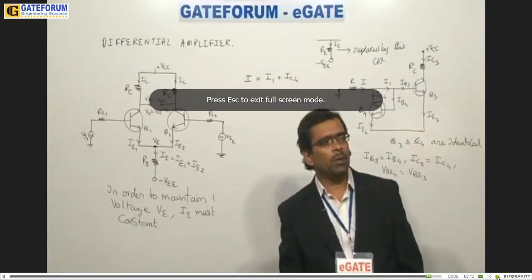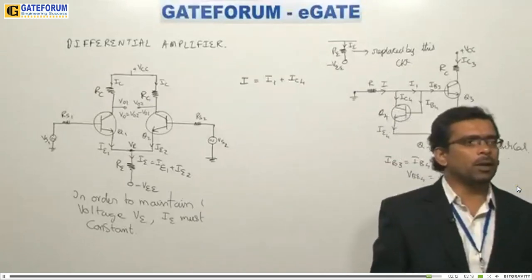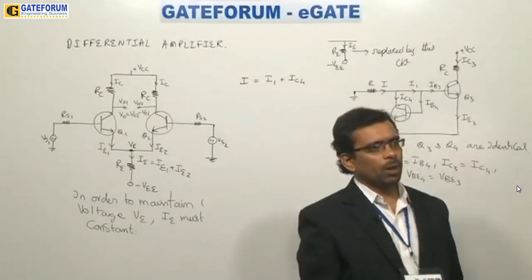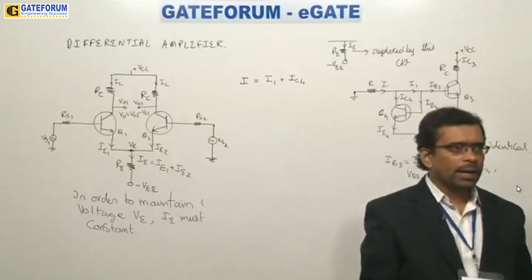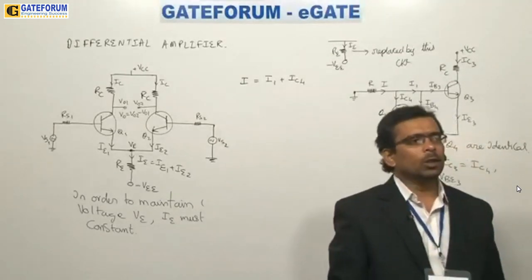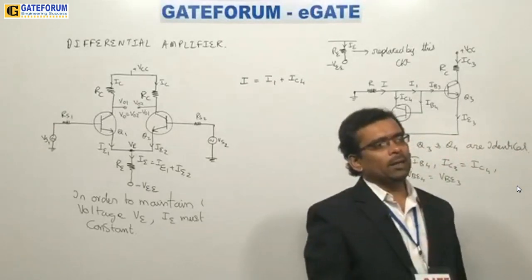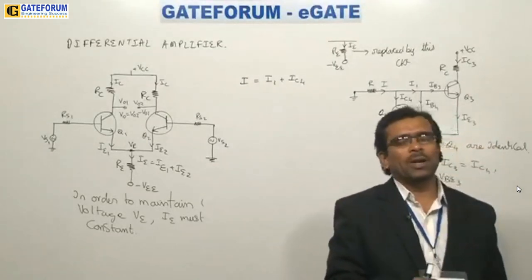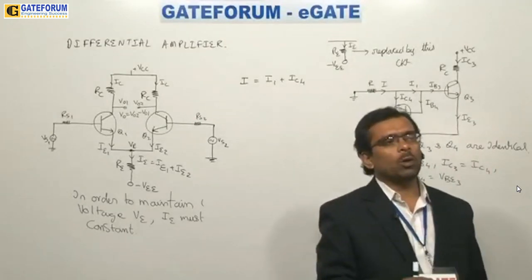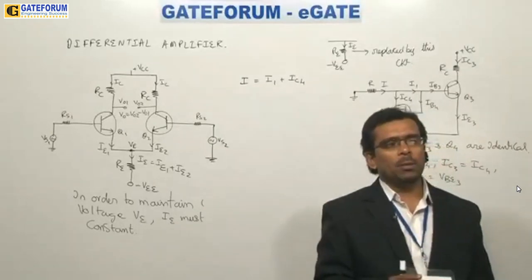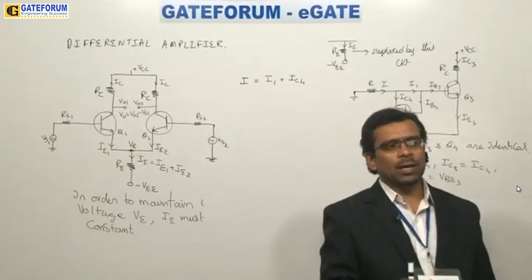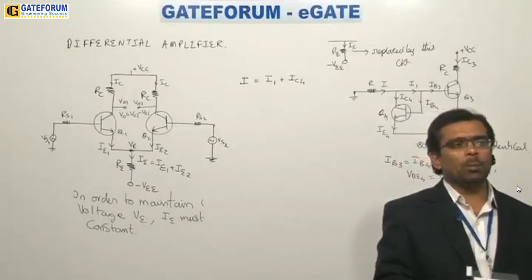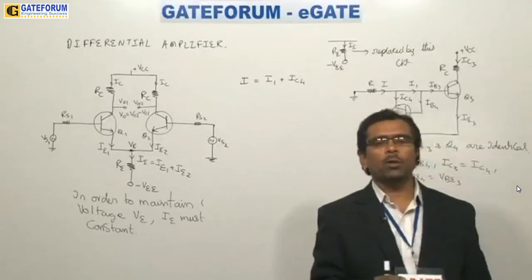A 1 mega ohm potentiometer is connected in series with RB. Determine the range of possible values for VC for the network using the potentiometer. So you are saying 1 mega ohm, and already you have connected 150k, right? So if you observe that, you change RB, 150k, into mega ohms, that is multiply by 10 power 3 divided by 10 power 3, then you get 0.15 mega ohm, plus 1 mega ohm, because you have connected a 1 mega ohm potentiometer in series with RB. So add those two, and it becomes 1.15 mega ohm.